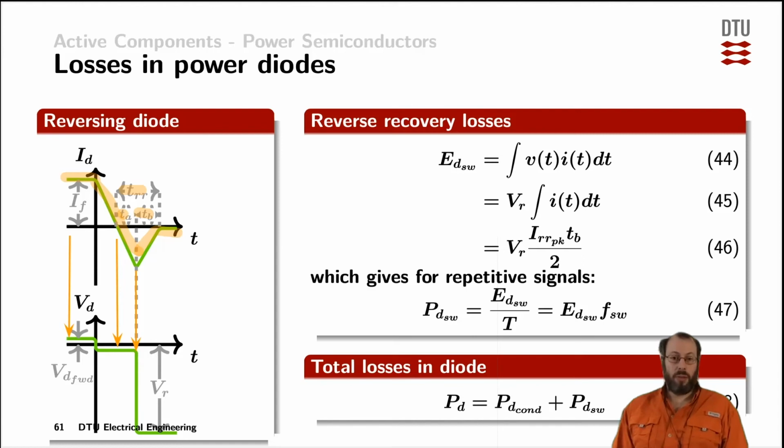In the case of the buck converter that we've looked into, that means that the switch is fully on and the switch is connecting the switching node of the buck converter to the input voltage, and therefore the diode starts to reverse bias and block the whole voltage beginning from the time where the current reached the maximum reverse recovery peak, and then onwards until the diode starts conducting again.